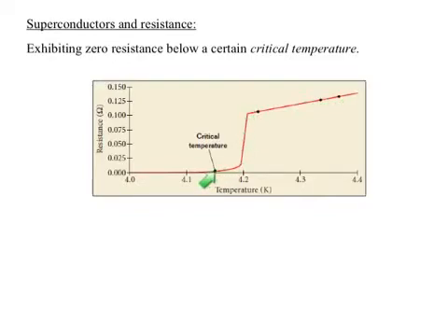And then we have something called a critical temperature. At every temperature below this, in this case it'd be 4.15 kelvins. Okay, every temperature below this, the material exhibits zero resistance or negligible resistance. And what would happen here theoretically would be if you applied a sudden voltage to a circuit, it would continue forever and ever. If that wire were cooled enough, nothing would ever stop that current from flowing around. It'd be like a frictionless surface. That's what this really is. There's very, very little resistance or little friction stopping it.